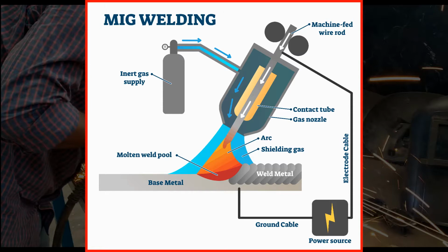Just remember, inert gas supply is used for saving our work metal. Direct atmosphere contact can be avoided by flowing the inert gas. The inert gas makes a layer above the weld zone and avoids direct contact of the weld zone with the atmosphere.